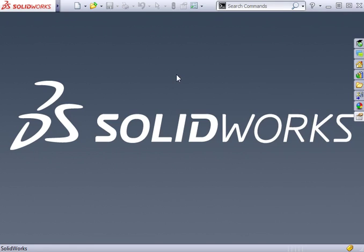One more area I'd like to quickly point out that has some additional resources is this area here on the side of your screen that appears every time you launch SolidWorks. It's called the Task Pane. The Task Pane is simply a flyout window that can be expanded when using SolidWorks. If the Task Pane is not visible, you may have to enable it by going to the View drop-down menu and select Task Pane. To expand it, simply click on one of the items stored in the Task Pane. To hide it again, click anywhere outside the window.